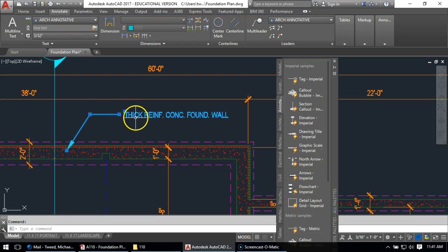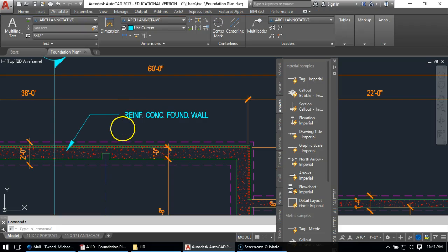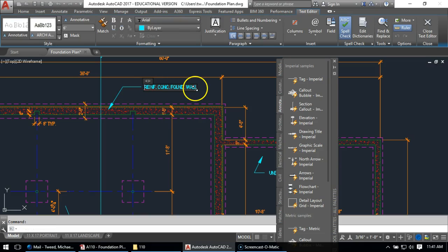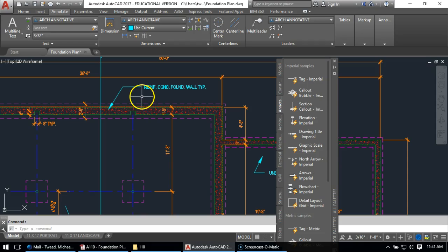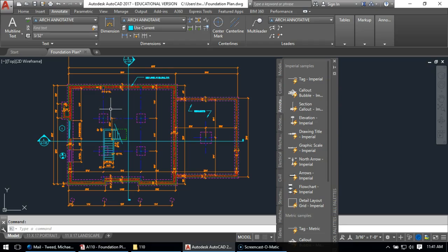The important part is that this is a reinforced concrete wall, and then you might look to find some detailing about that on another page. So I'm just going to say reinforced concrete wall. Then I don't need the 8, I don't need a 12. It's just all that way. In fact, I might even change this further. Double click to edit it and do TYP, and then know that, hey, all my concrete walls, they're reinforced. That makes sense. I won't take off if you do it the way the instructions instruct you, or if you do it this way.